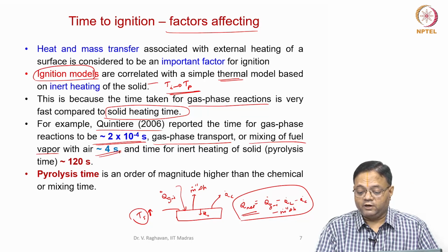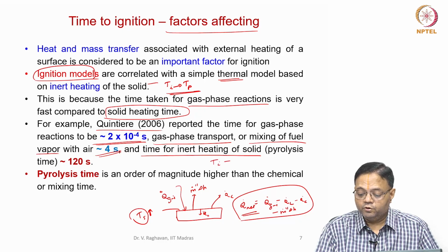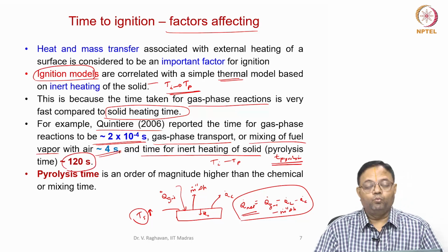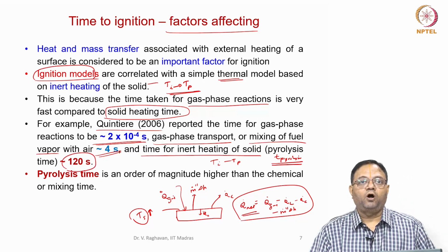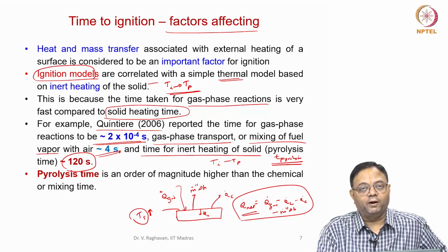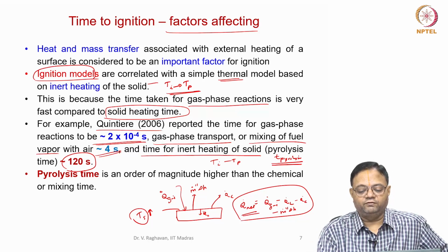But the time for inert heating of the solid, that is the pyrolysis time, will be about 120 seconds, order of 100 seconds. So, order of 10 power minus 4 seconds is the gas reaction, which is very small.